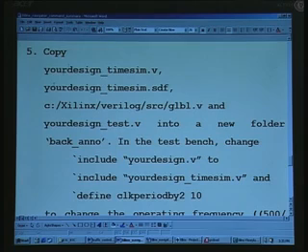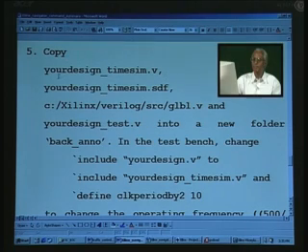So, we have already got that maximum frequency reported in one of the files, serial number 2, that we have already seen. What you do is, although it is not necessary to copy it to a different folder, it is good practice to do so, because you will not confuse it with your design file, and especially the test bench, which you need to modify, because now it has to reflect the back annotated file instead of your actual design. For example, if it is RTC, this is what the Xilinx tool has created, and it is good practice to have it in a different folder. So you put these two back annotated files that you have just seen, as well as the library file.